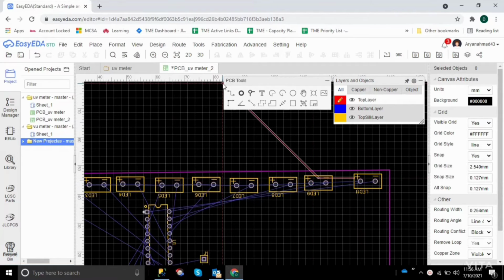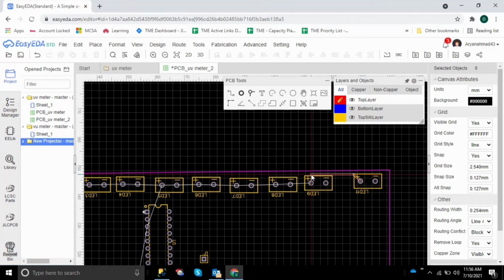And this is a pencil tracer. Put the pencil tracer and draw a line, click here, and now you can see the other layer disappears, because right now we are making this one. You can also select the thickness of the wire in the upper zone, but I am using a standard 0.5 mm, because it is a low voltage circuit.